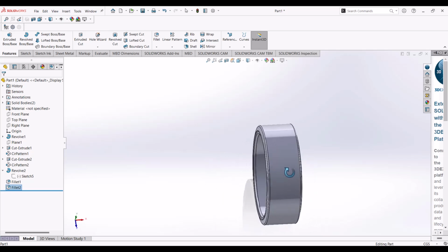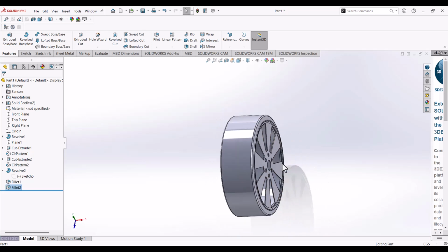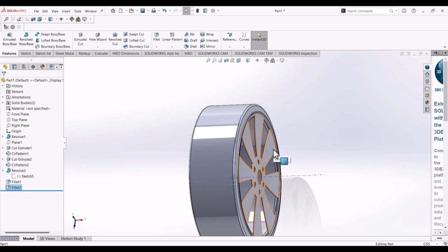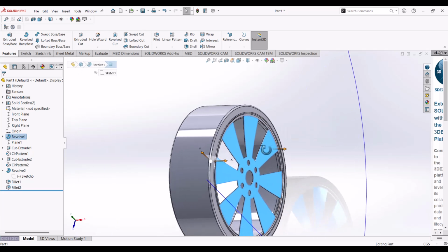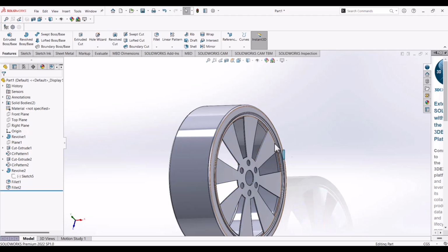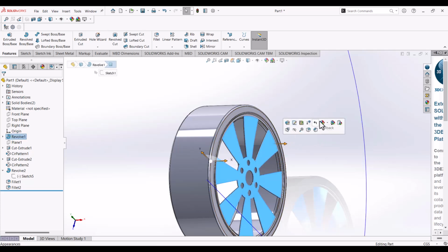Okay. Yes, and there is this thing I didn't speak about. We call something appearance, adding appearance to an object. That is basically rendering it. So what you do is, let's click on this surface. You see, immediately you click on this surface, there's this pop-up. Here you have appearance, copy appearance, paste appearance.